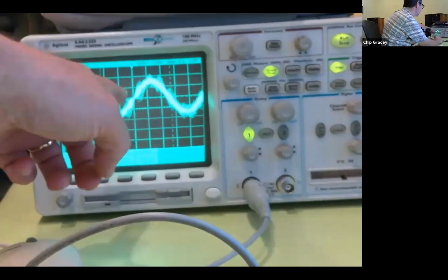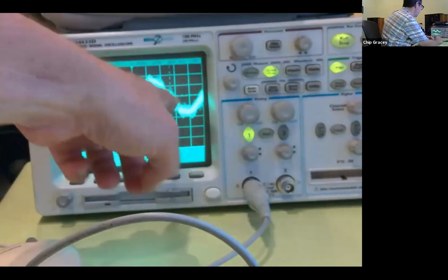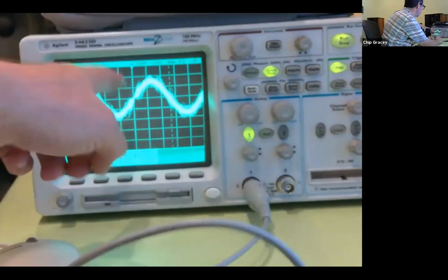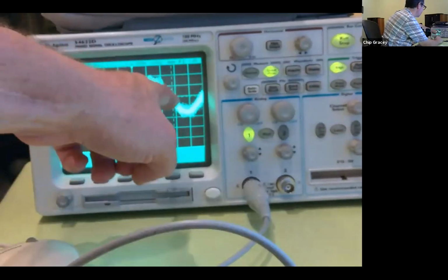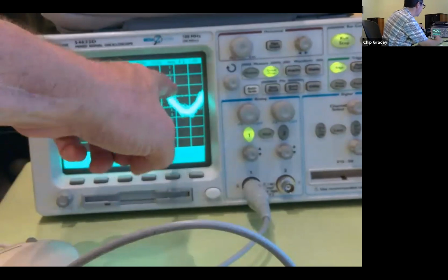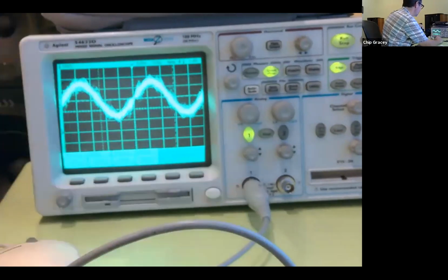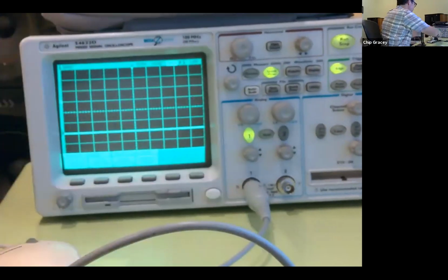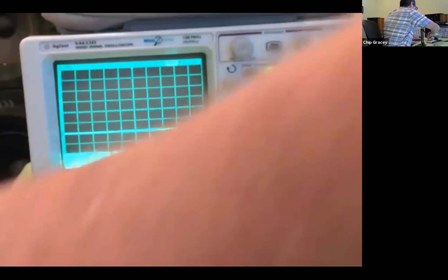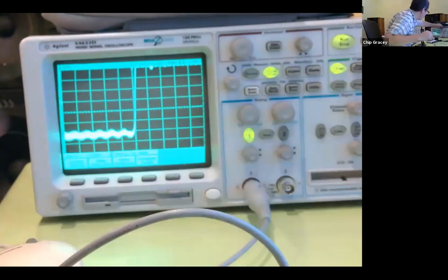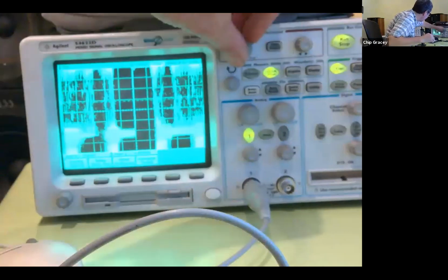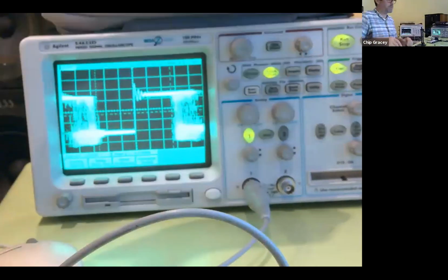You see all the noise? Very, very noisy. This is re-triggering as it crosses the boundaries. It's getting more than one clock pulse, which is upsetting the PLL and causing all this net jitter down on P0. Okay, so this is the problem we've had.